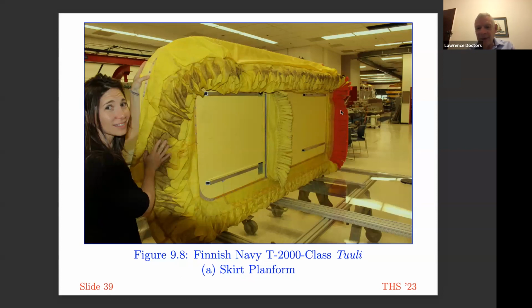That red material, I don't think there's any significance to the color, but there is significance to the material. The inside surface of that trailing skirt is a bit stiffer than the rest of the skirt. And so it's providing a kind of planing surface there, and perhaps some sort of physical protection against wear and tear.